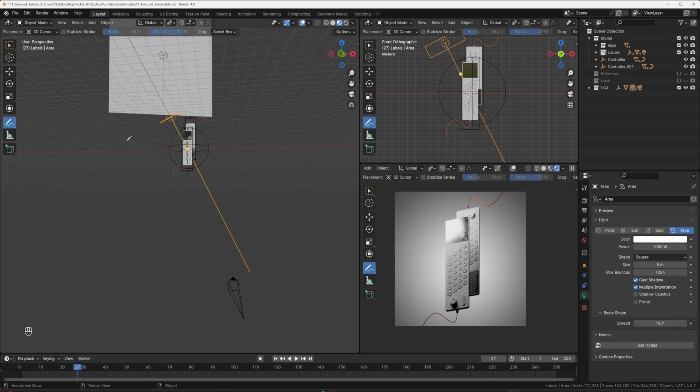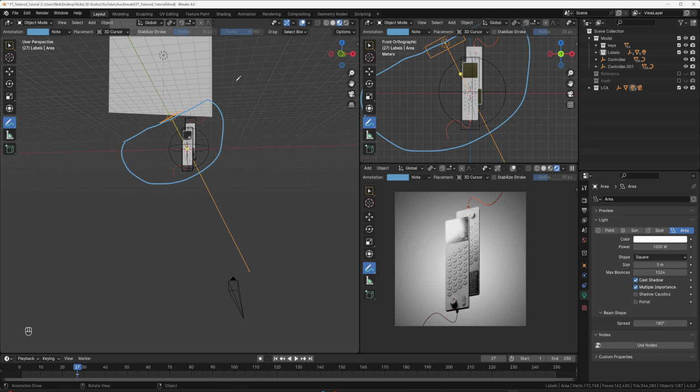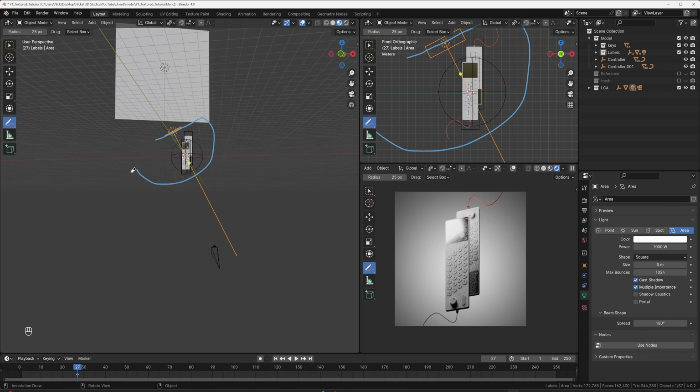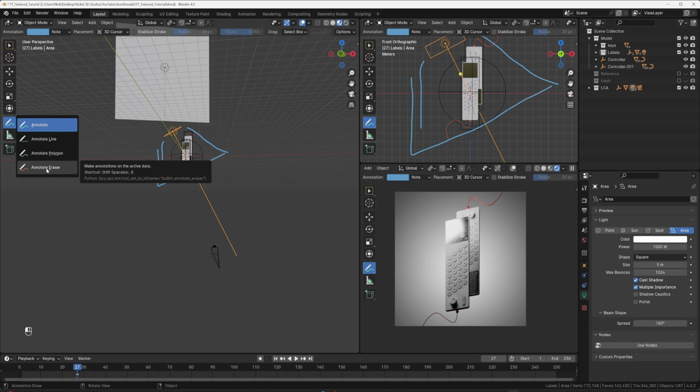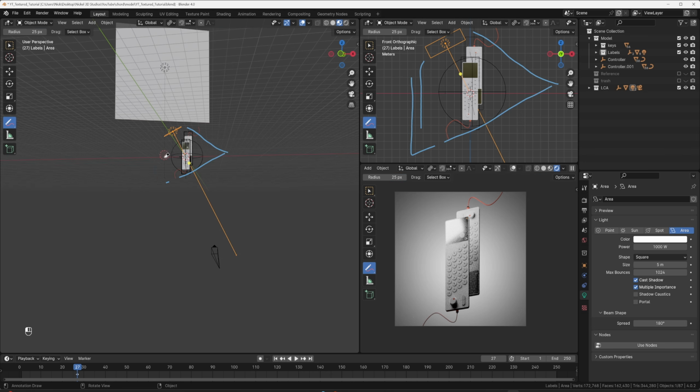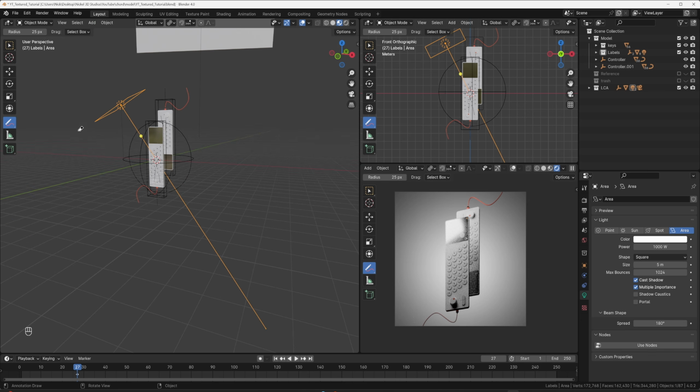Instead of light coming out in 180 degrees like this, so you can tell that this is half of a circle, it's a bad drawing. Instead of that happening, as you decrease your spread, instead of being all the way out here, this light's going to get pulled in more and more like a spotlight. Sometimes that really helps you to have some nice falloff, because you can adjust the blend on the light also, and that's going to let you create a nice gradient falloff. So we're going to use that in our scene here.